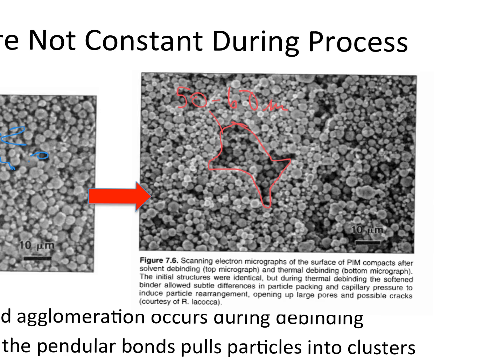Now, sure, if you stick it in the furnace for a long enough period of time, you might be able to eliminate those large pores, but it's more time and money to do that. So better to make this microstructure behave and not turn into that microstructure. Does everyone see that? It's not just density, is what I'm saying. These could have similar densities, but you've rearranged the matter on the interior to generate pores, flaws that can lead to failure of the part downstream.